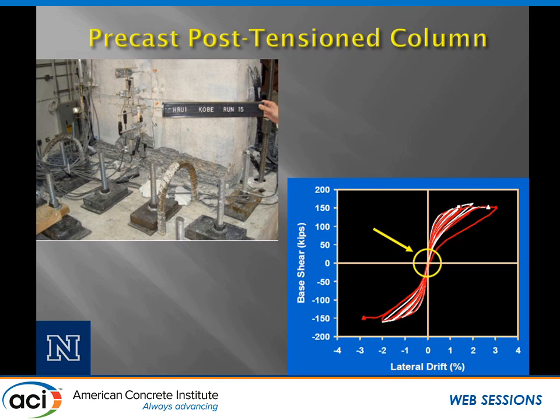But the issue is, of course, energy dissipation. How do you dissipate energy? But if you can dissipate that energy through another mechanism, maybe through a combination of a base isolator or some other slider or something else in the system, you don't have to do that in the column. Therefore, after the event, you've got this recentering capability and you've got damage that's very easily repaired.